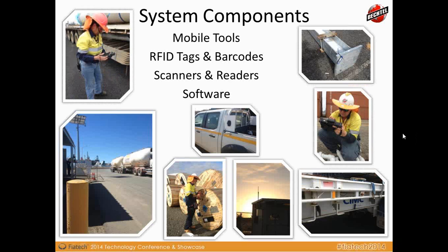So we have 13 gate readers which are installed at the entry and exit of all the facilities, including the lay-down yards that you saw on there, the spool fabricator, the port facilities, and the locations that enable the cross-harbour movement. There are 4 vehicle-mounted readers used at different locations. The main reason for those is to help us calibrate any movement in locations, because even though these things are set down and tagged to a given location, if you've ever been on a project site, you'll know it's organised chaos and things tend to grow legs and move on their own. So we have the vehicle-mounted readers that help us recalibrate where things are.